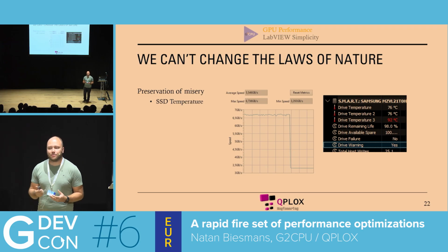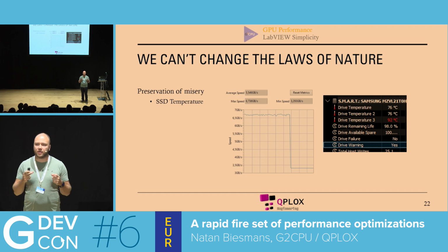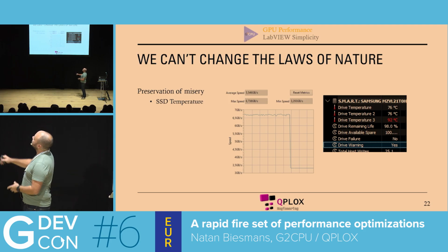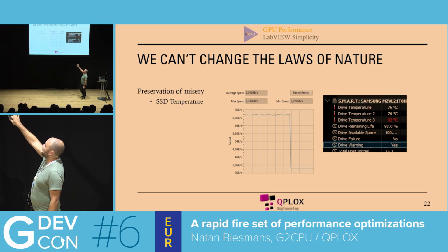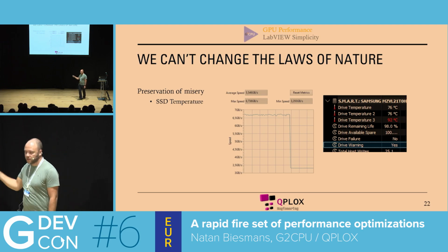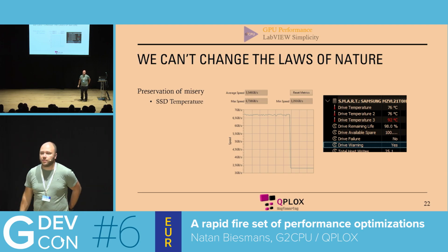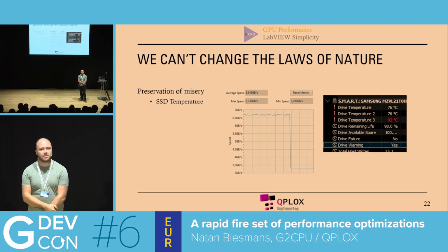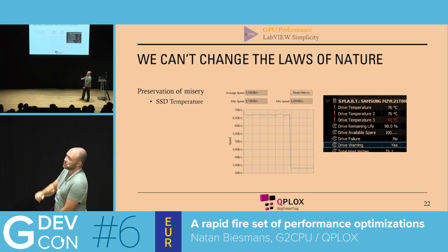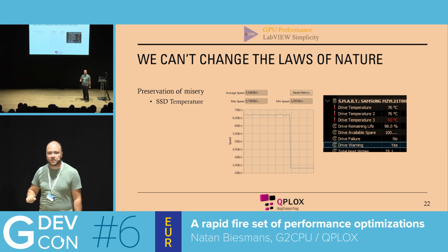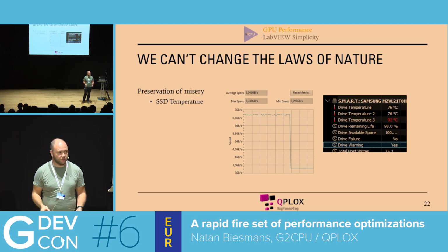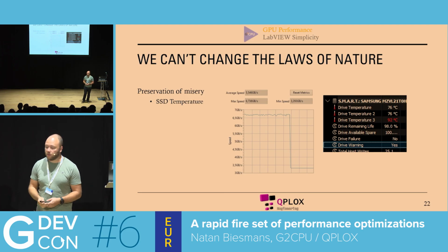First of all, modern systems, these SSDs, they're becoming smaller. And suddenly we need to start considering temperature. As you can see here, we are reading at between 7 and 6.5 gigabytes per second during this run. Probably chunks were not that great. And suddenly we see a dramatic drop to about 3.2, 3.3 gigabytes per second. Not only that, if we go into the statistics, or the information on the drive, we can see there is a warning. And you can also clearly see drive temperature going to 92 degrees Celsius. This is the drive protecting itself. That's the first problem, something we need to consider.